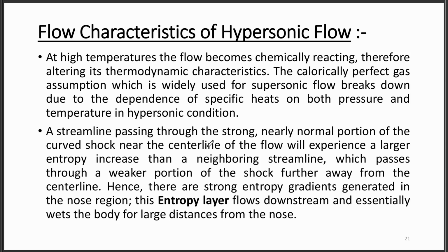The assumption of calorically perfect gas, which we used for supersonic flow, we cannot use for hypersonic flow, because both Cv and Cp will depend on both pressure and temperature in hypersonic conditions.